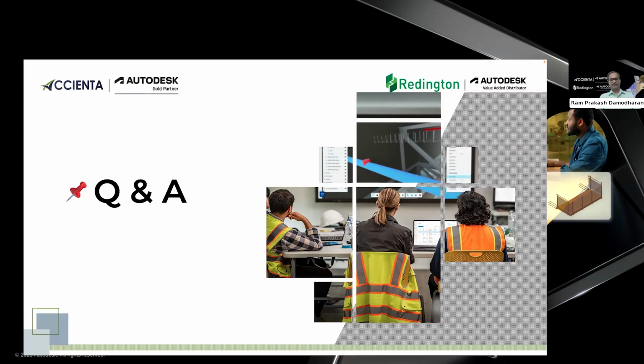So for the configuration of a machine, I would say that if you are already using Revit for large-scale projects, where you use Navisworks for your clash detections, I think that should be quite enough to use Twinmotion, because what Twinmotion basically needs is a proper graphics engine. That's the same graphics engine that you use for your Revit, 3ds Max or Navisworks Manage. I think configuration-wise it's good. In a general way, the configuration which you use for your Revit projects, which you see works fine, you can take that for Twinmotion as well.